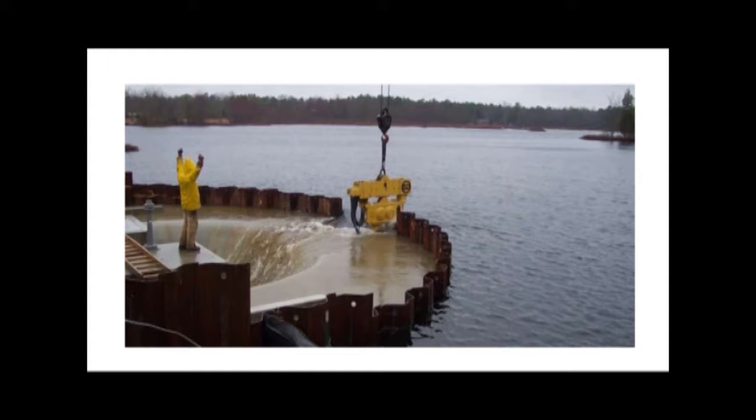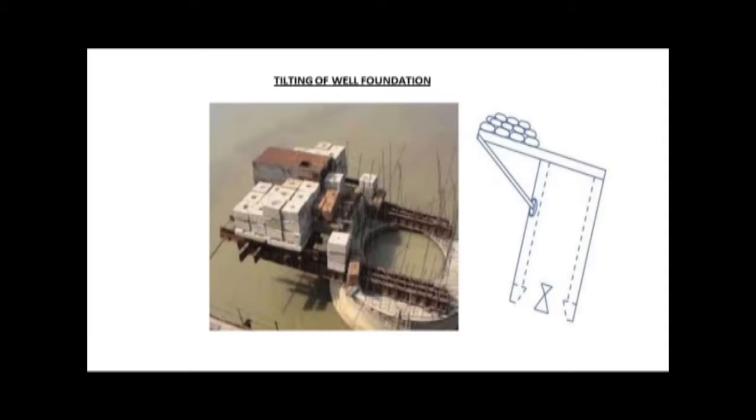So what the intermediate plug will do is, between the bottom plug and the intermediate plug there will be nothing, but between the intermediate plug and the top plug we'll fill it with sand, so we have reduced the quantity of filling. At the top of it we provide the arch epoxy slab, and then we have the pier or abutment. It can serve as the base for the pier as well as for the abutment.